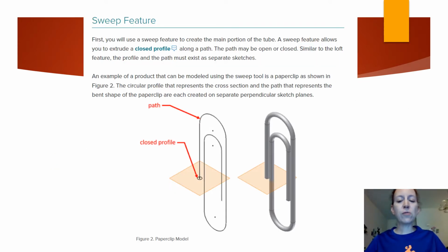So first, we'll talk a little bit about the sweep feature. You're going to use the sweep feature to create the main portion of the tube. And what a sweep does is it allows you to extrude a closed profile along a path. So the path may be open or closed. The figure that you are sweeping along the path will have to be a closed figure. All that means is that it is...